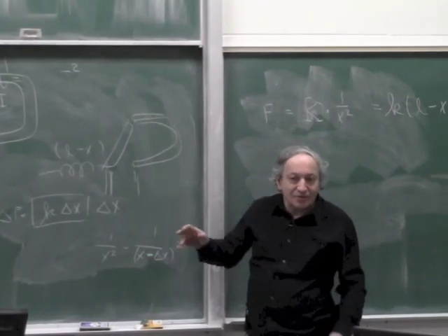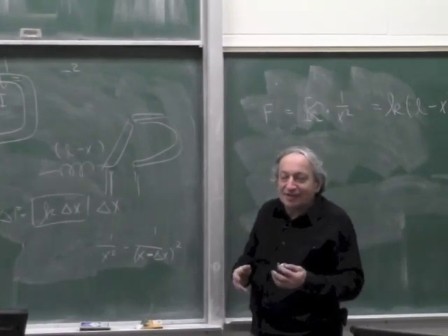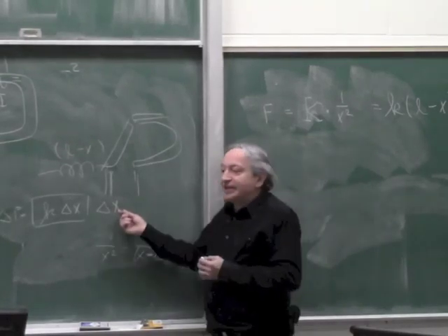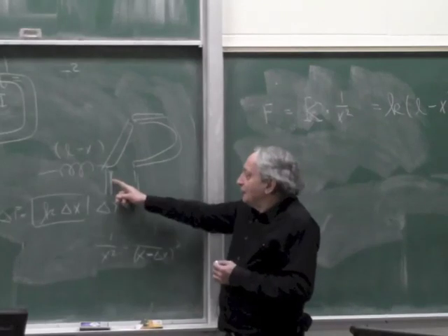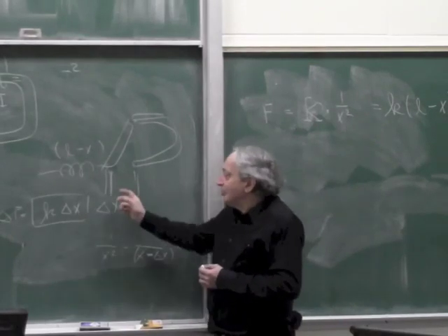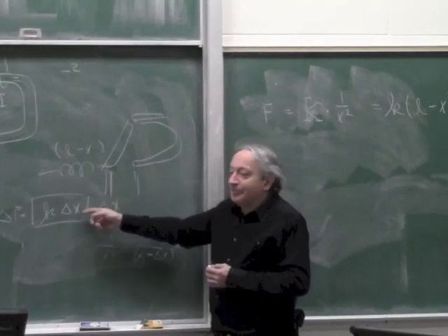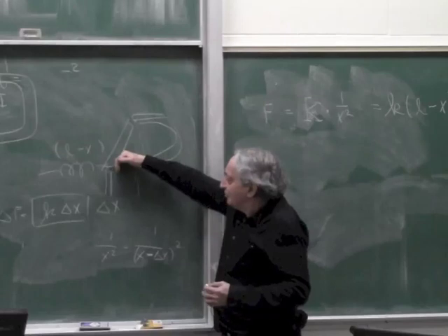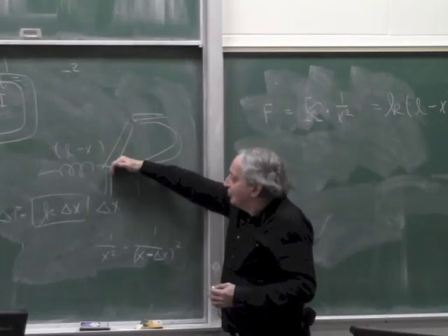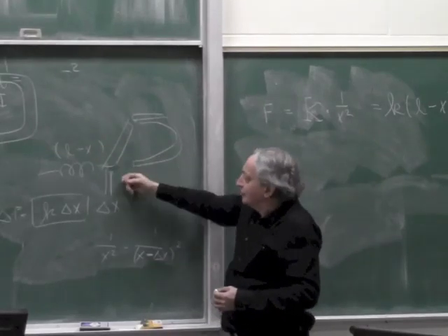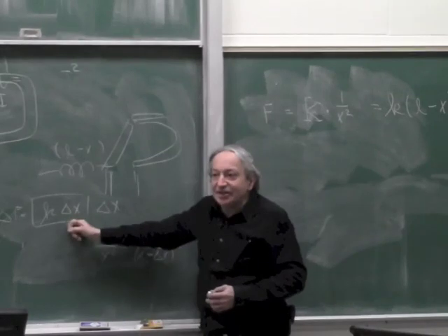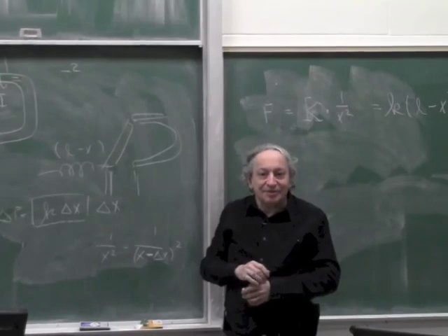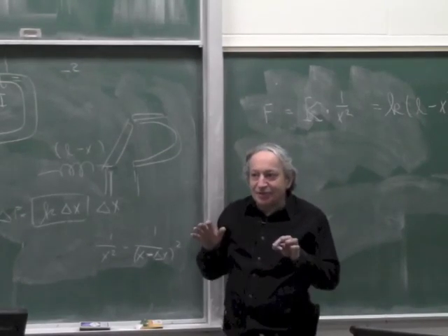Okay? So how would I formalize it? When I look at this, I say, at some point for a change delta x, this increase in force will be equal to this, and beyond that point, this increase in force will be bigger, so there will be a runaway situation. Because if it came to the point where moving in delta x will increase this force more than k delta x, it will keep moving until it snaps. It becomes unstable. Okay? So is that clear intuitively to everybody?